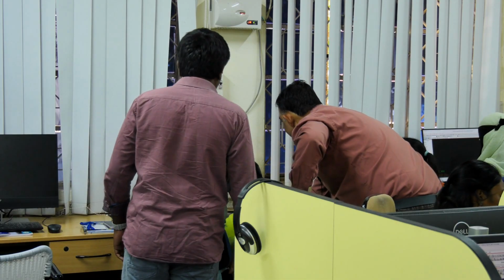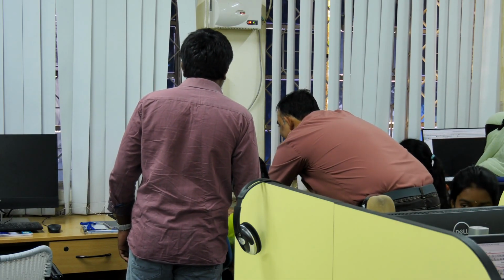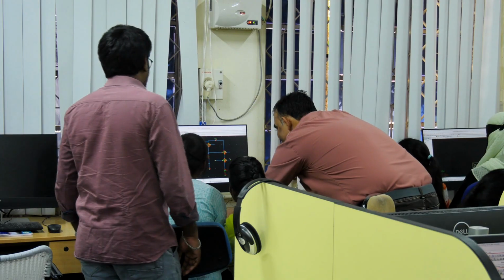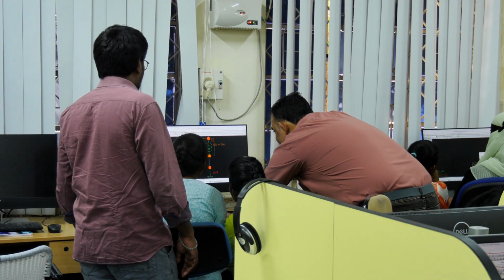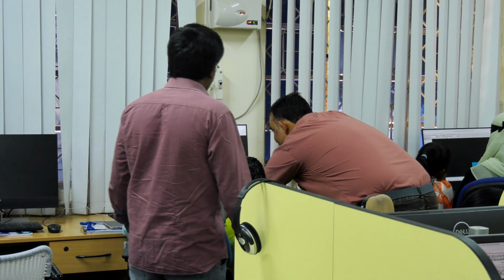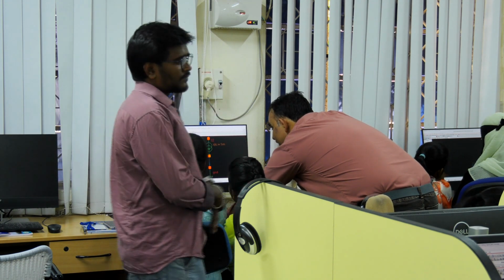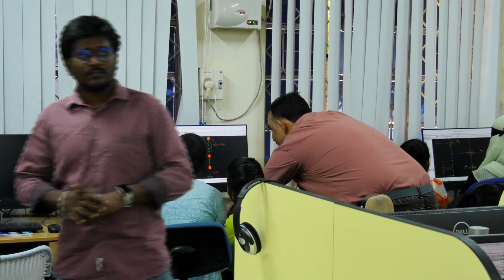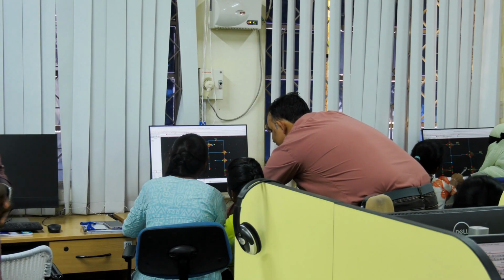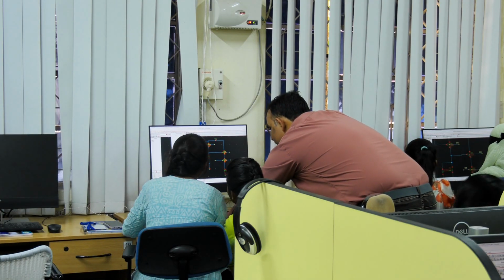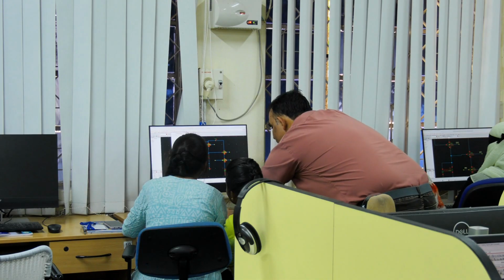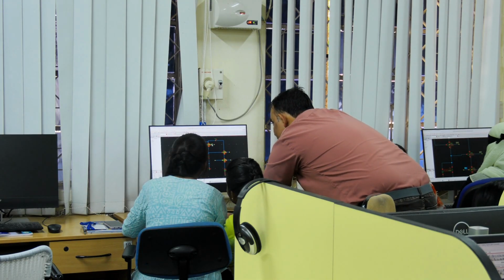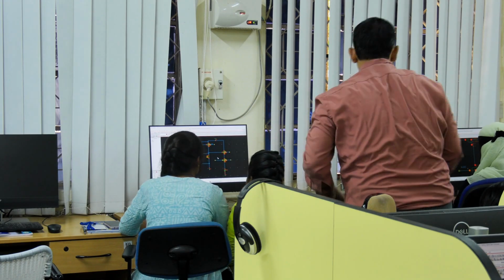So what I will do is delete all of these and do it again. Much better than trying to figure out. And these two are not connected. So you only have 9. These lines, all of them should have a name. Similarly, ground exclamation, and this should be VDD exclamation mark. Once you have done that, then run.